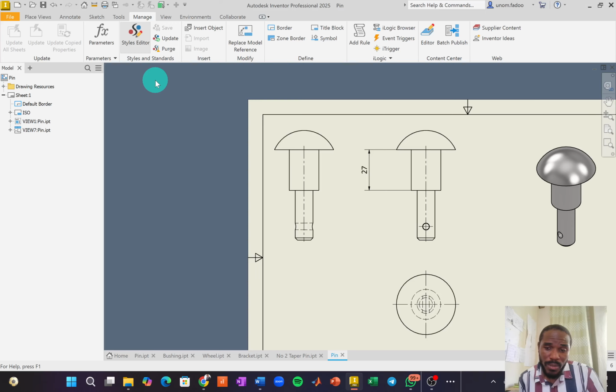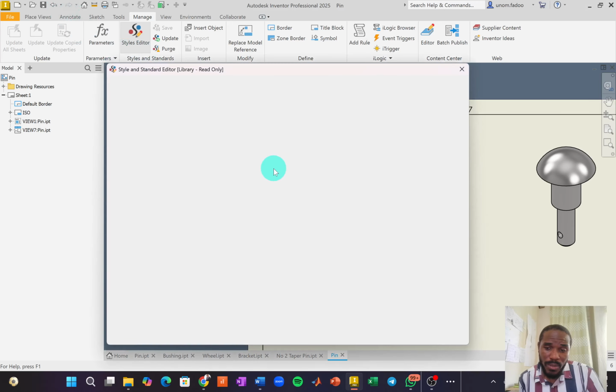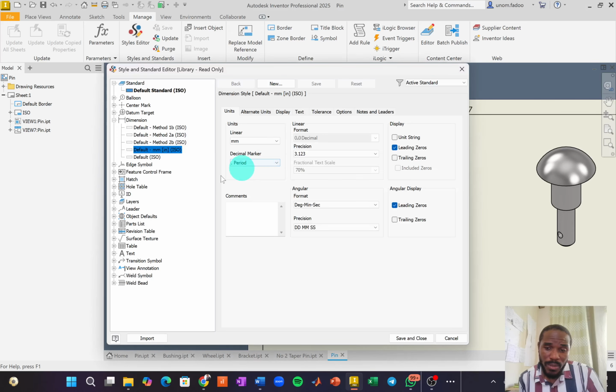So basically, while that is coming up, you see that all you are doing, Inventor would retrieve the dimensions that you've used in building this. So you are not going to be writing it yourself. However, you can override. Okay, in the annotate, there is a place for overriding. You can override a given dimension.